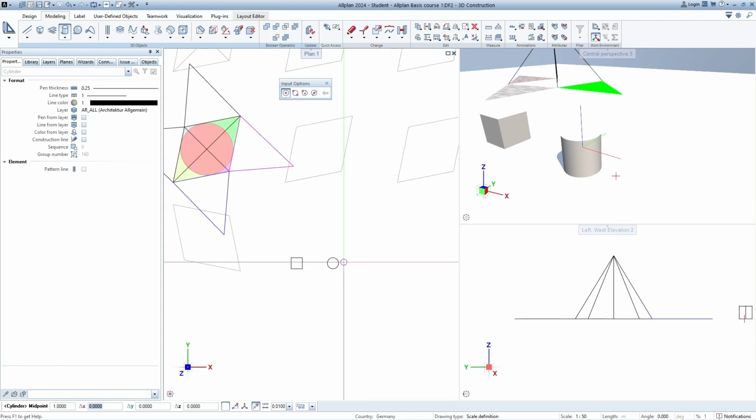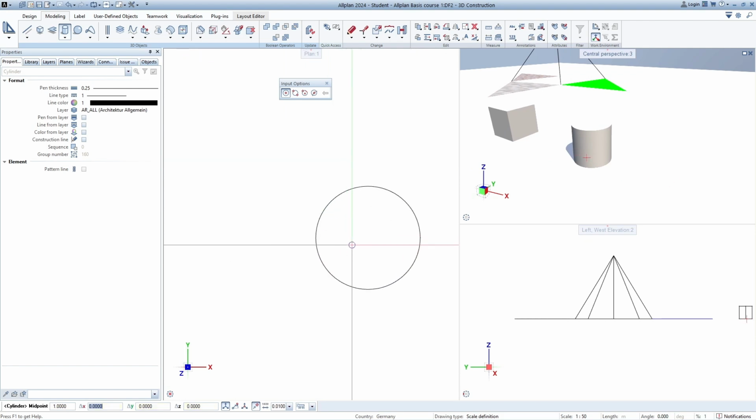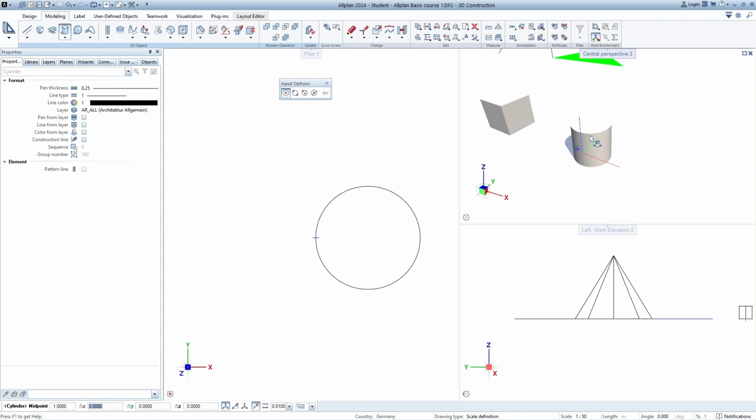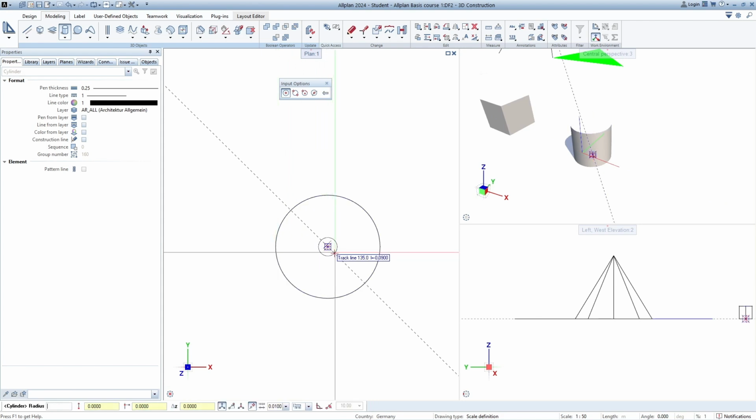Our goal here is to basically add another cylinder exactly inside of the cylinder. Why would we do this? Because we want to create some kind of pipe. And the pipe should have a thickness of 10 centimeters. So how do we do that? So we are going to generate another cylinder inside. So what I did, just do a right click on the edge of the already generated cylinder.